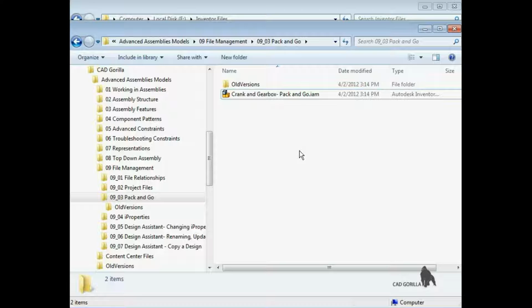While it's important to have all of the files, it's just as important to copy the folder structure. As you've seen, Inventor stores the file locations in the assembly. This means you would have to go through the file resolution process for each assembly if the file locations are different. Pack and Go is a utility that copies all files related to an assembly to a new location.